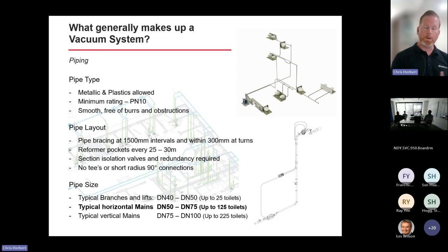So if we're not moving that waste quickly through the pipe work, we might start to get hang-ups in there. We might get some struvite or uric acid build up in there over time, and we might get to a 40 or a 30 mil bore, and then we're going to start to run into some issues. So we want to make sure that we're keeping that system working as efficiently as possible. We've got the waste moving as fast as possible, so we can really leverage that small bore piping, which is another one of the great benefits of vacuum drainage.